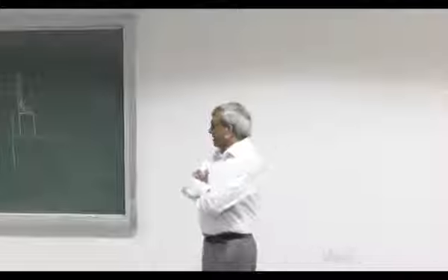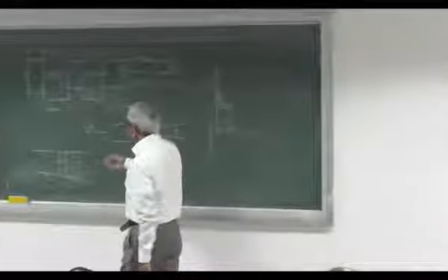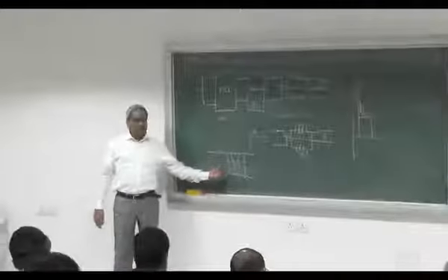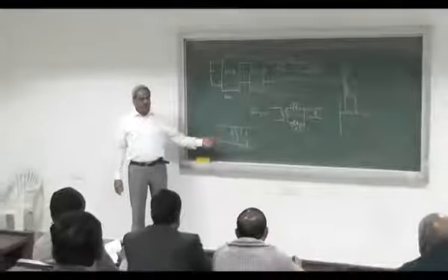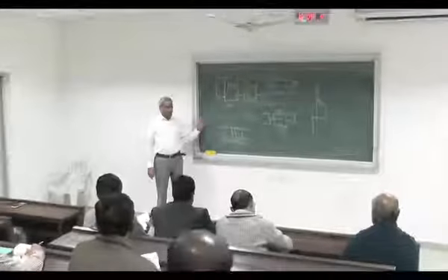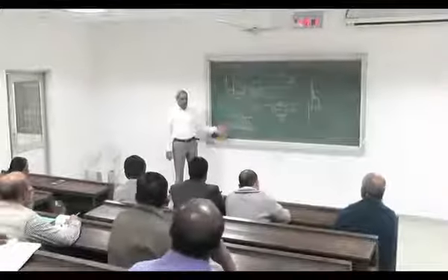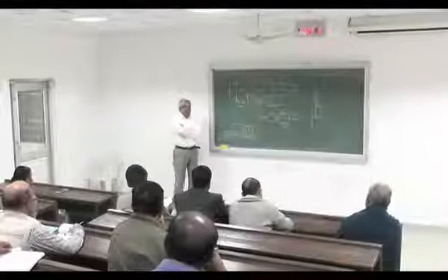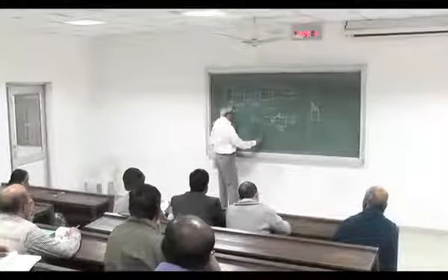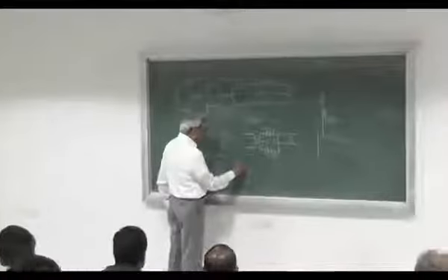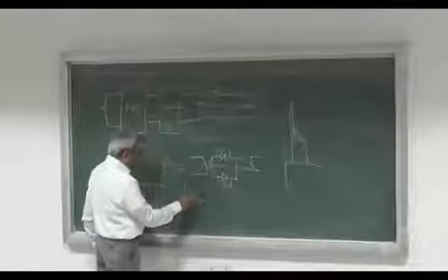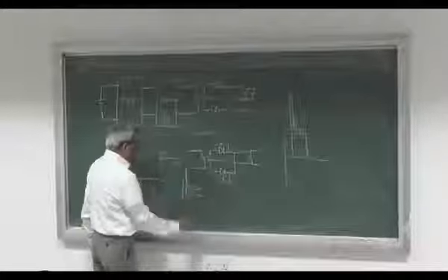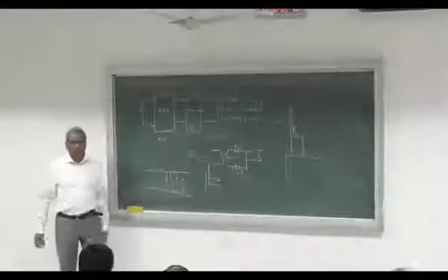Depending on the turns ratio, this capacitor could be quite significant, and again depending on the current and power and other things. So you may not see this kind of current shape which we want, like this. You might see some kind of strange looking current waveform.